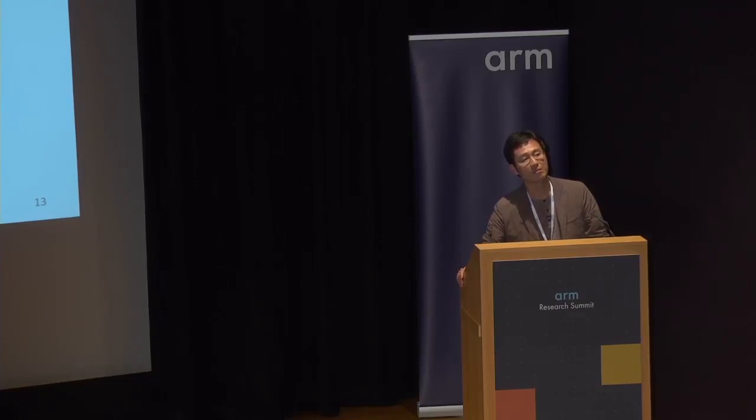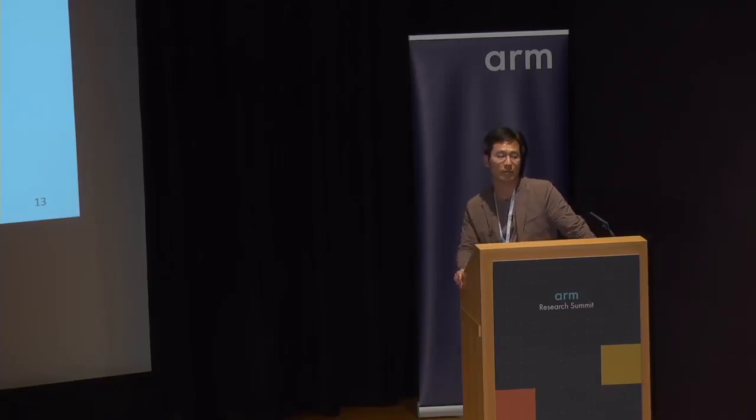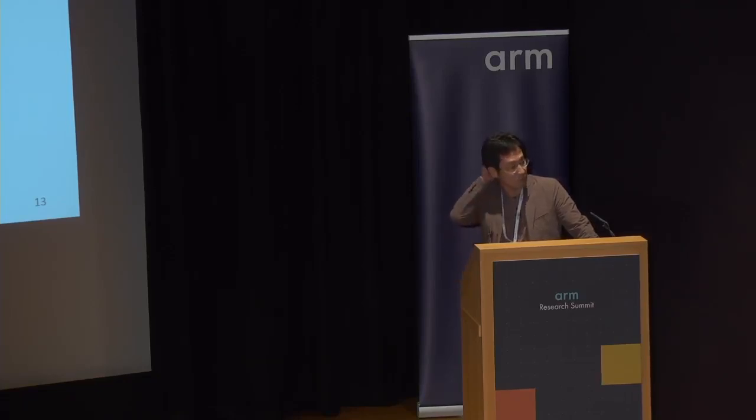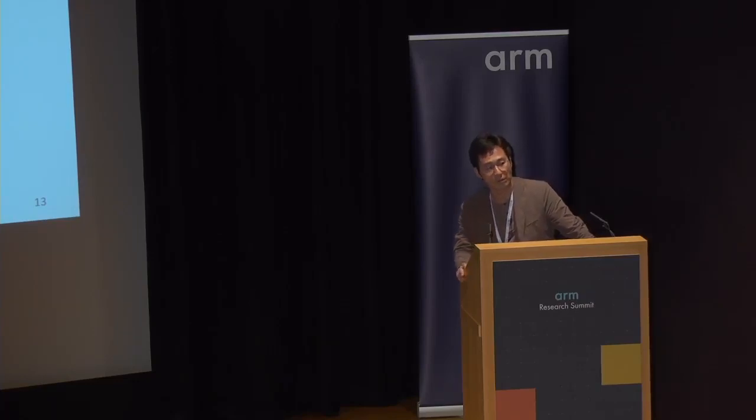Sure. So we assume that the memory is protected and there are no errors in the memory. The errors are only injected in the execution, the processor pipeline, right? The pipeline. So the pipeline is not considered protected. The memory is considered fully protected. In all the components of the processor pipeline, like the six components he mentioned, including the register file, decode unit, load store queue, buffers, and reorder buffer, we inject errors in all of them, and that's the result.